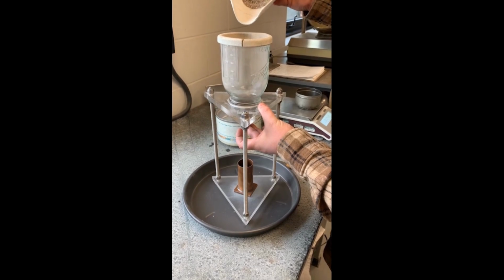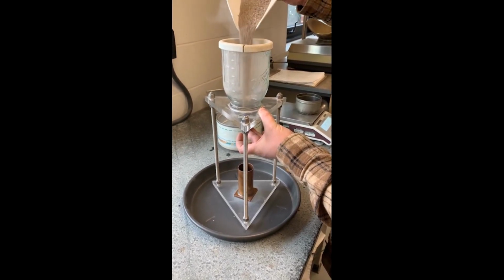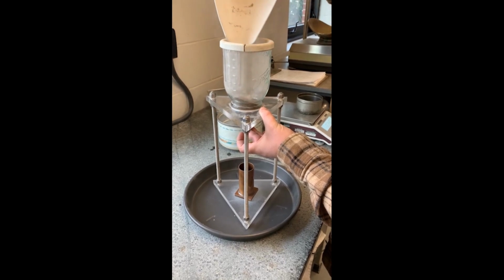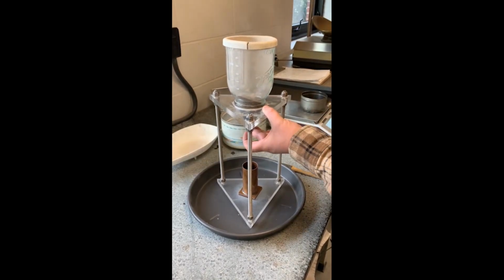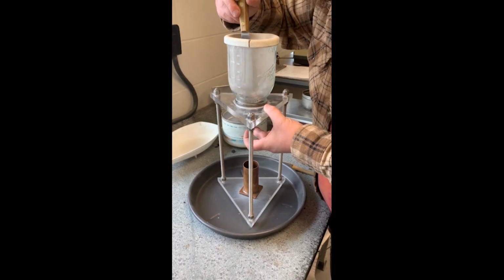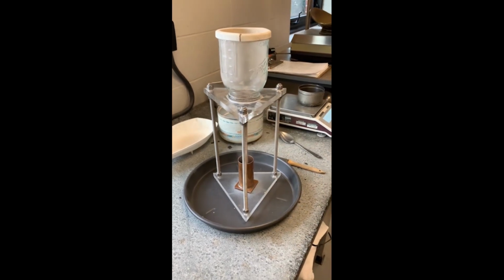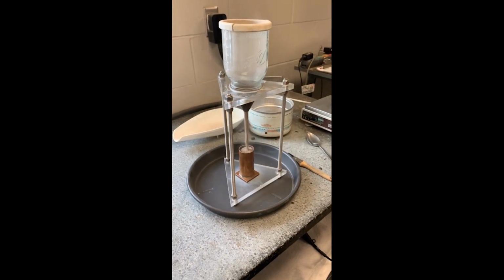After the aggregate is thoroughly mixed, place a finger underneath the bottom of the funnel and pour the material in within 4 to 6 seconds. Level the top of the mound, then remove the finger from the funnel and pour into the brass cup.